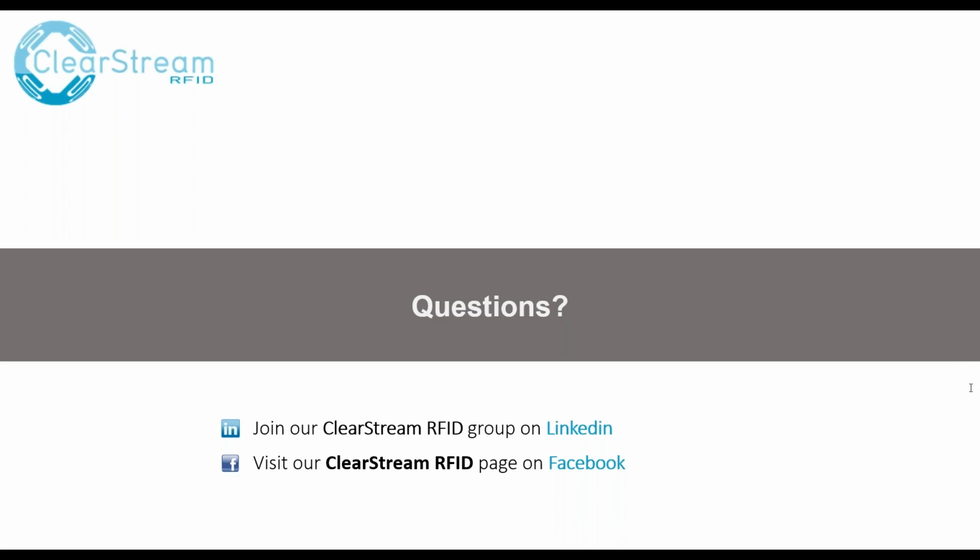Can the software be set to only read triggered reads? For example, a scan gun that has a trigger on it versus an auto scan. I think if you want to have the reader only reading at a particular time based on activity, that would be the general purpose input, that GPI area that I mentioned in ClearStream. You can have the fixed readers have a certain number of input ports where you can hook up buttons or motion sensors or photo eyes and things like that. And ClearStream will completely support the ability to have that trip the read.